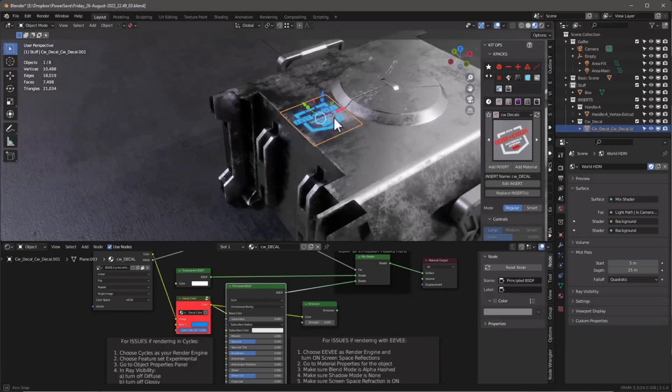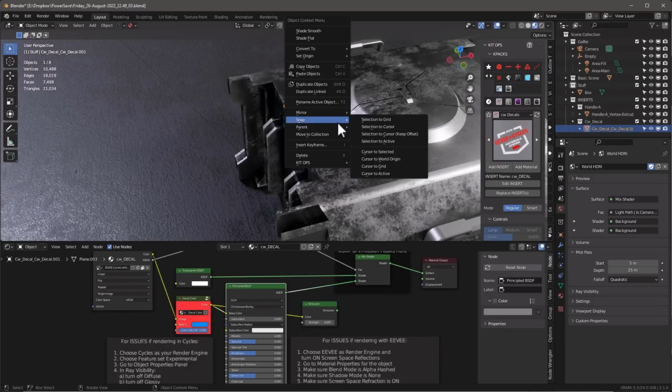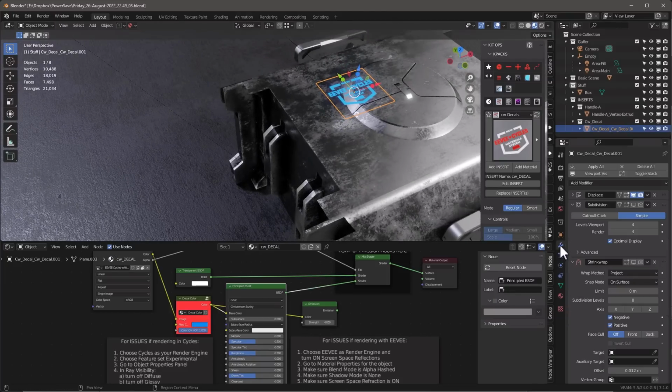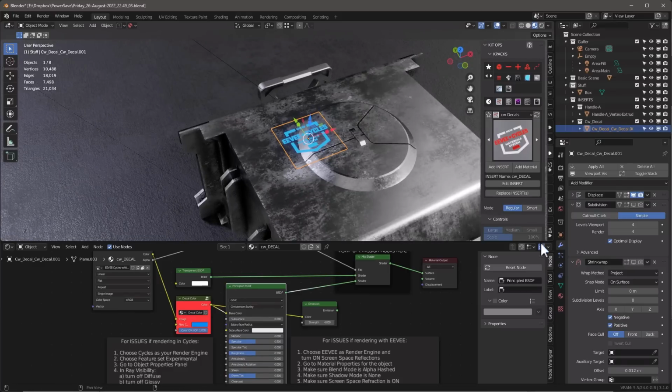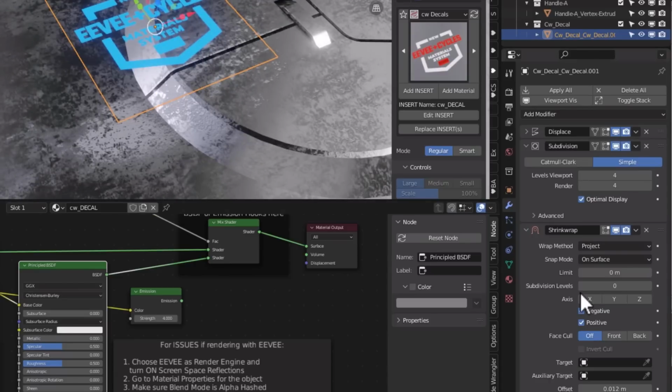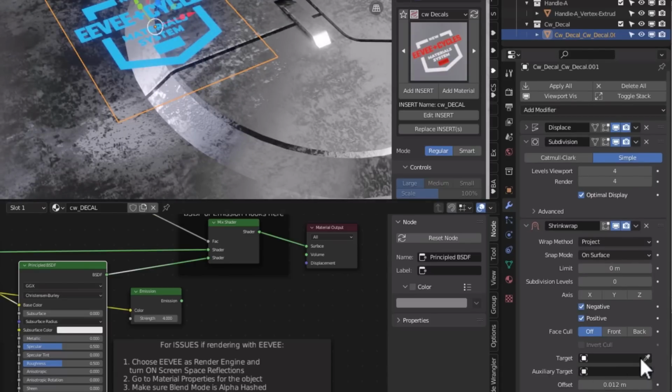And the other thing to mention is that if we right click and say relocate this insert, and let's put it right there, I can come over here in this object and I can hit this shrink wrap, right? Right now it's turned on. Let's put the subdivision on and we'll turn on the shrink wrap. Let's turn these both on. And with it set like that, I just need to basically say, what is my target?